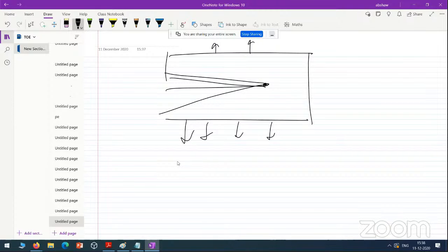So this is the information you have in this problem, that there is a singularity at the tip of the crack. If that singularity can be used while choosing the field, your final solution will be very close to the actual solution.